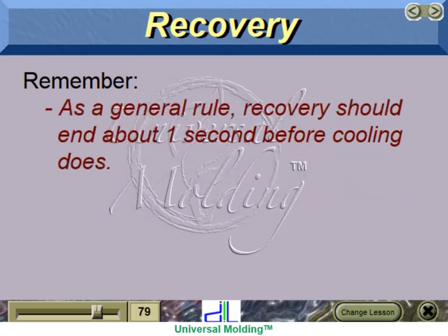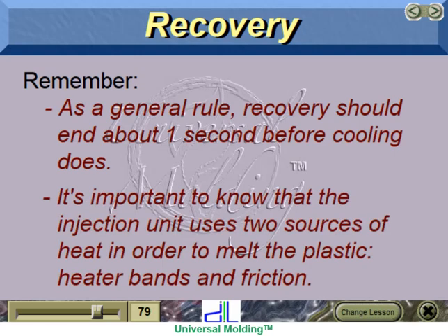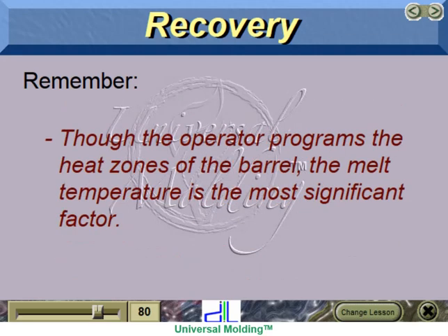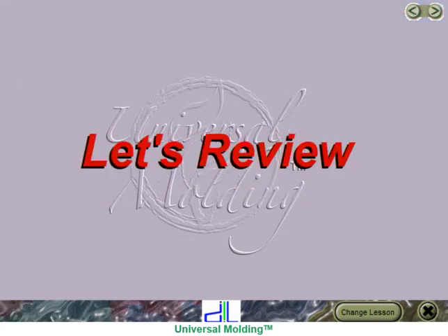As a general rule, recovery should end about 1 second before cooling does. It's important to know that the injection unit uses 2 sources of heat in order to melt the plastic: heater bands and friction. Though the operator programs the heat zones of the barrel, the melt temperature is the most significant factor. Let's review.